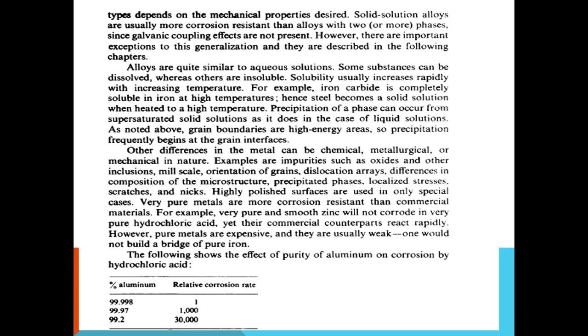As a result, these point defects at the surface lead to adsorbed atoms or vacant lattice sites. There may also be sites of intersection of dislocations with the crystal structure at the surface. It is easier to remove atoms from kinks or ledges than from other surface sites.